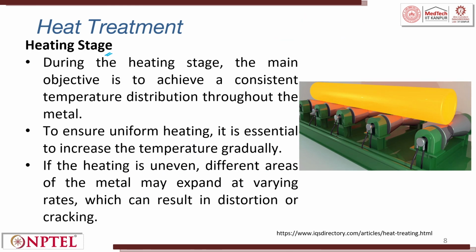Heating stage. During the heating stage, the main objective is to achieve a consistent temperature distribution throughout the material. If there is improper distribution of temperature, you can have thermally induced stresses. These stresses can warp the material; the shaft can warp like this, because there is not a uniform distribution of temperature.